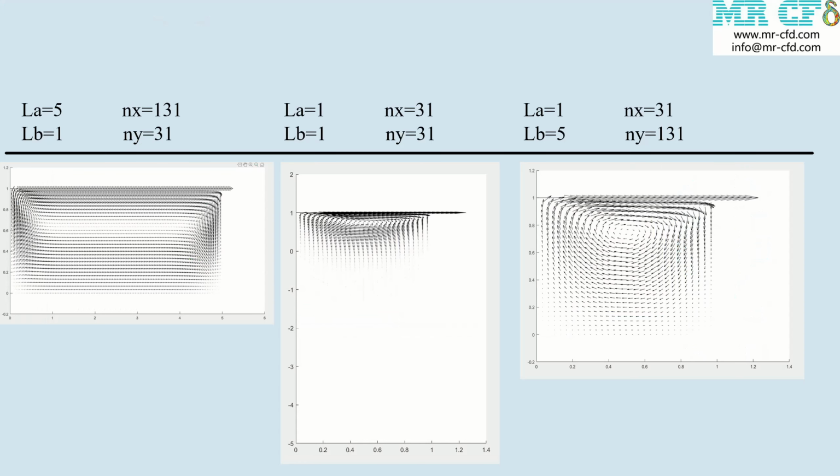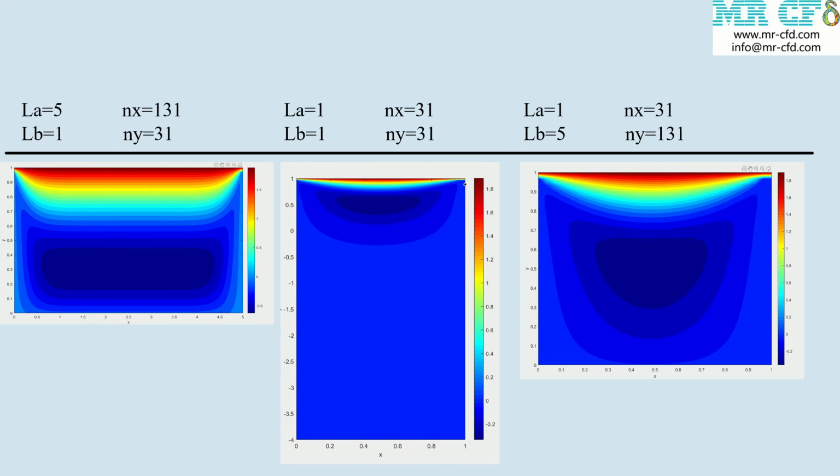By altering the dimensions of the cavity geometry, such as increasing its length and depth, you can run the code to obtain results for various cavity types. This allows you to observe the flow patterns within the cavity. In a cavity with greater depth and shorter length, you'll notice that the effect of the velocity at the top of the cavity does not easily diffuse to the bottom. Also, the u velocity for each of these scenarios is presented here.